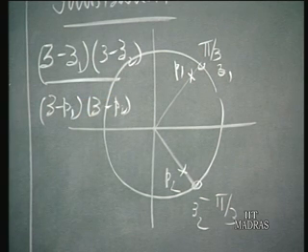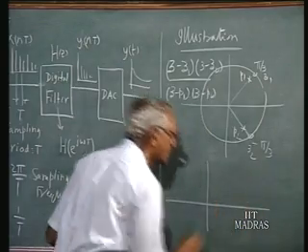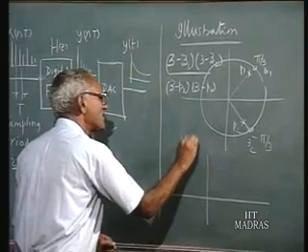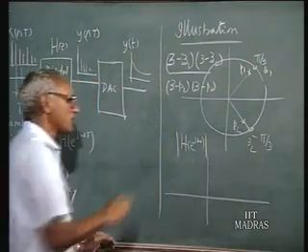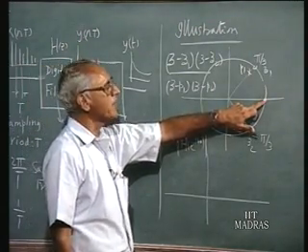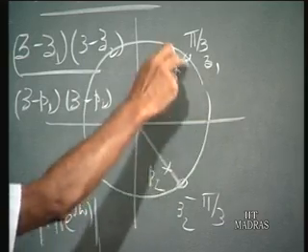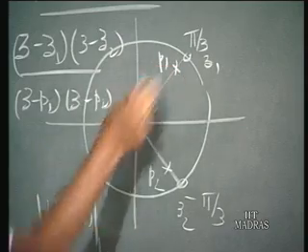So what will be the frequency response of this? Suppose we ask, then the answer will be, the magnitude of H(e^{jω}) is what we are plotting. Now at this point, that is the DC value, when ω equals 0, the distances from that point to Z1 and P1 are nearly the same because it is very close to this.